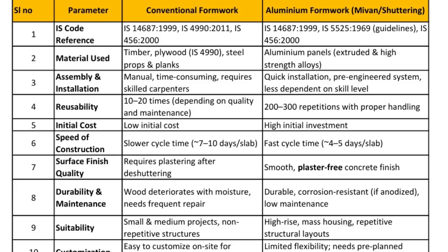because it is an aluminum extruded alloy, and we use the shuttering oil, the form release oil, and it gives a superior finish. Sometimes you don't need any plastering work, but the conventional system always needs plastering, so extra cost is involved. For that also, the aluminum formwork is the number one choice.